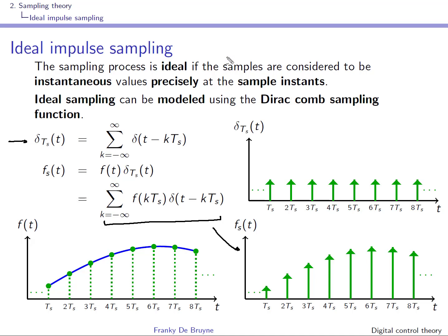So really what is important is, if you know f(t) that you're sampling and you know its Fourier transform F(omega), the question is, can we obtain also the Fourier transform of this sampled signal, which we'll call Fs(omega)? The relation between these two will result in the sampling theorem.